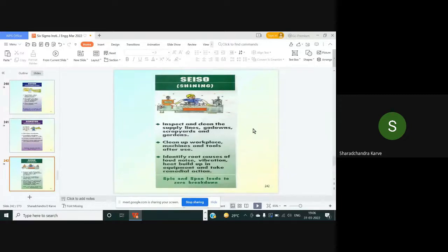So if they are working on some machine or equipment, or if you own a car, probably the concept in Japan is they themselves will clean the car, so that they understand whether there is anything missing, or something leaking, or going out, or indicating any problem, so that they can identify the root cause of the same. So the concept here is listen, look, and feel. Listen for a loud noise, feel for vibration, and look for anything abnormal happening at the shop floor.